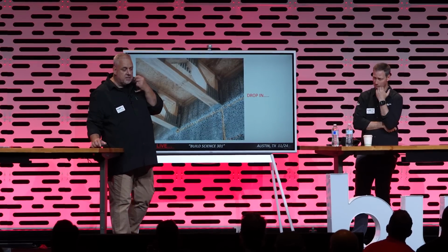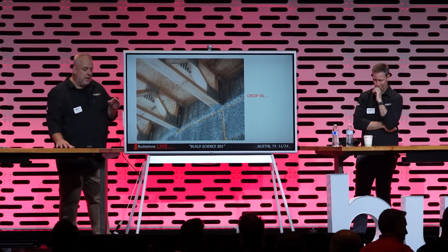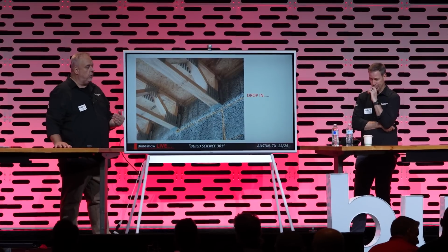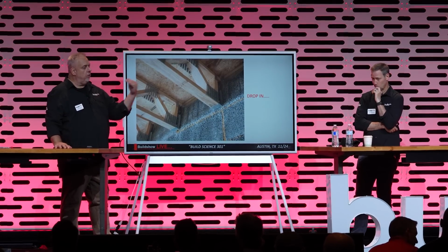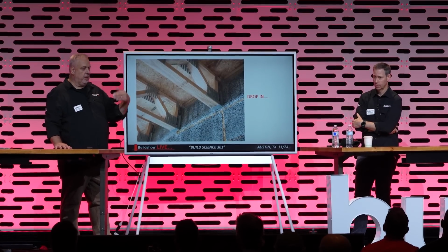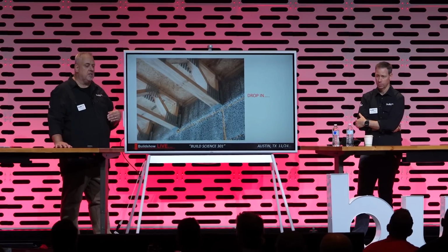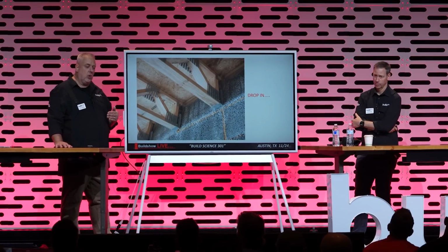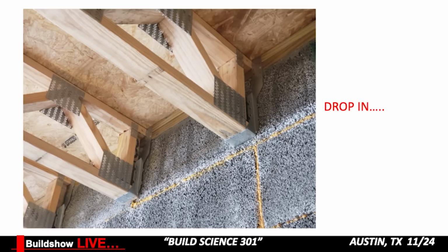One of the things about this system here that we did was we did a drop-in floor frame system. So the whole floor frame is thermally inside that condition space. That's smart. And we just have that top cord bearing truss going out. And what that does is it takes our 28 inches delta from subfloor to grade and reduces it down to about, maybe about 10 or 12 inches.